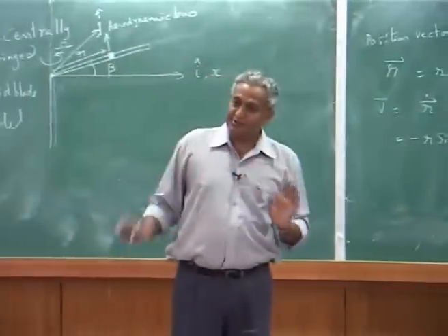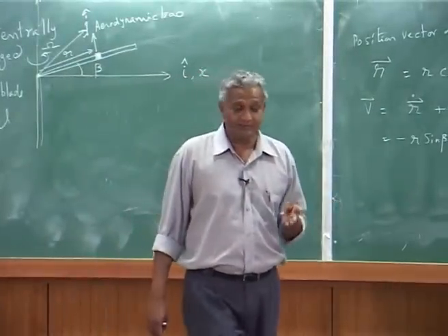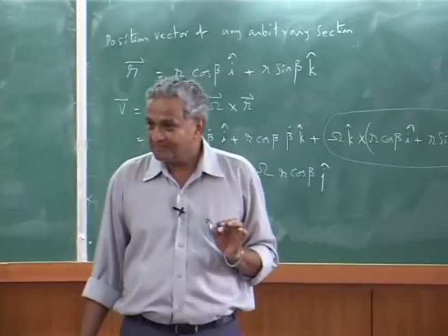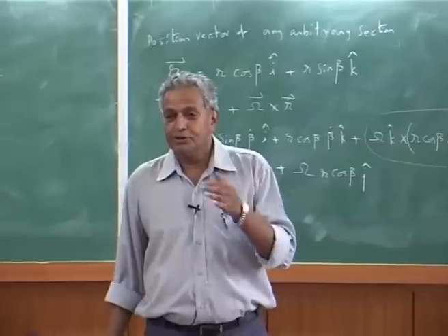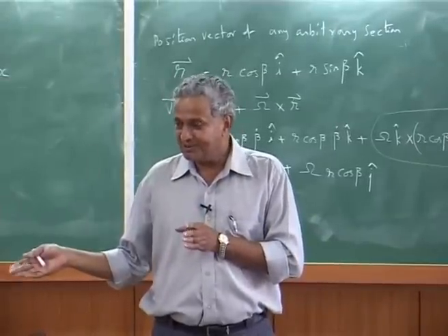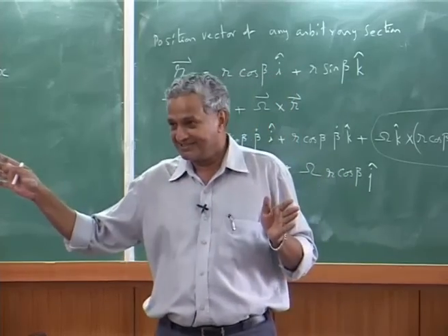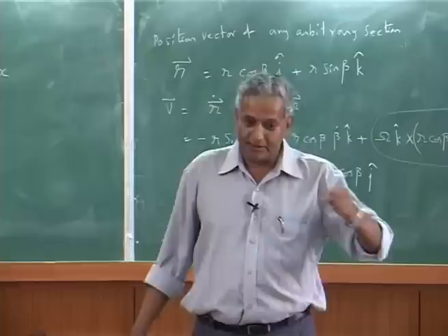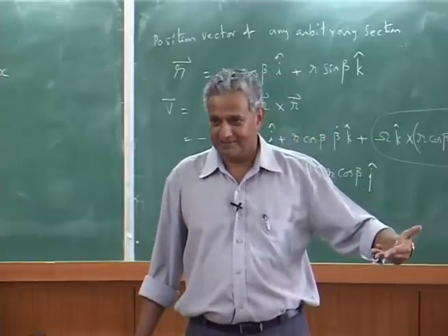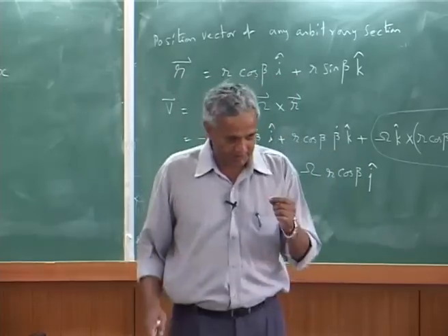You can directly use that expression. You have the relative acceleration, the Coriolis acceleration, the centripetal acceleration, and the angular acceleration. So you will have 4 terms. And if your hub is moving, that acceleration also will come. That is how you have to develop the acceleration of any point.